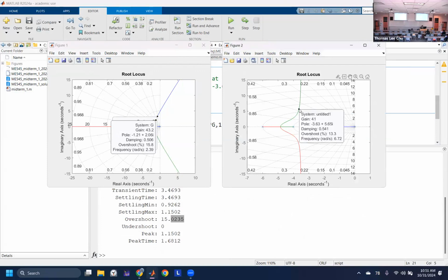And we're going to check if it passes through -6. So negative 3.61 is what we're looking for. And you can see how quickly the gain changes. And that's pretty close. Yeah, so 46.5 or 47.5, 47.3. You can see that this is basically the same point. Even the damping ratio is the same, 16% overshoot. Now, if you look here, you can see we actually have a closed loop pole as well along this point here.